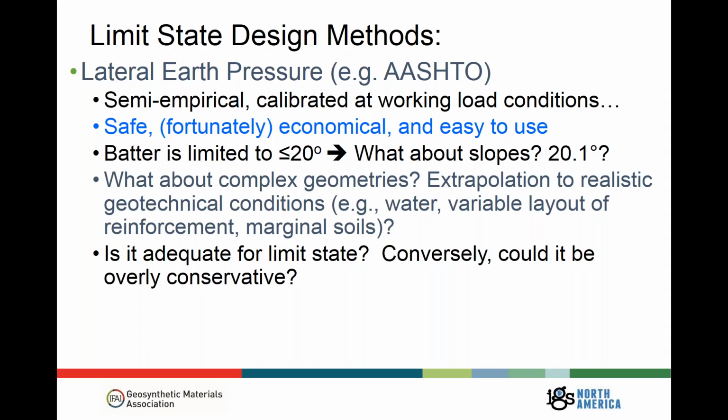Another restraint is that the earth pressure approach works great for simple structures, a simple MSE wall. Anybody who's designed MSE walls realizes that simple is a lot less common than complex. Often when we're designing a structure, we're dealing with difficult site conditions. We're dealing with a right-of-way issue. We're dealing with water. And we might even be dealing with other complex things, surcharging, other loads. Most walls are complex, and earth pressure theory does not so easily shift to account for these complex conditions. So it's tough sometimes to extrapolate these earth pressure approaches to complex yet realistic geometries.